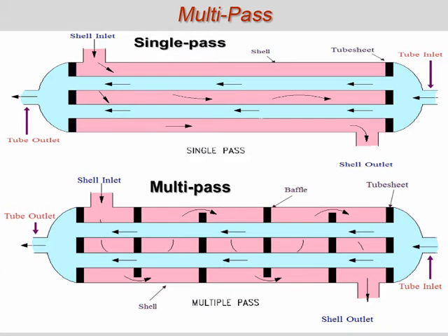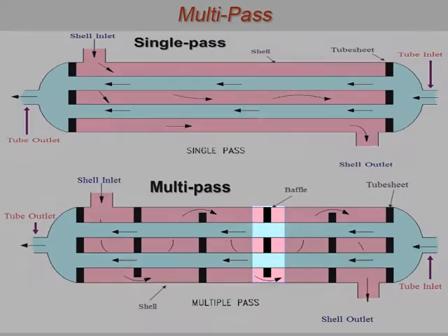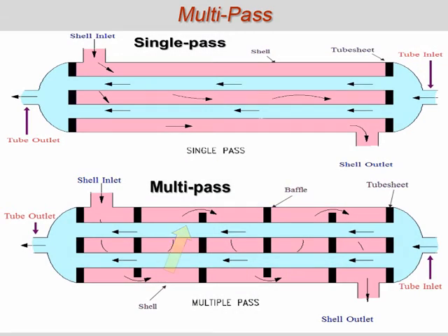When a heat exchanger's fluids pass each other more than once, it is called a multi-pass heat exchanger. If the fluids pass each other only once, it is called a single-pass heat exchanger. Multiple passes are achieved by inserting baffles on the shell side of the heat exchanger. The baffles direct the shell side fluid back and forth across the tubes to achieve the multi-pass effect. From the outside, the heat exchanger looks like a simple counterflow heat exchanger, but on the inside is a multi-pass counter and crossflow. You should become familiar with the parts of a multi-pass heat exchanger.